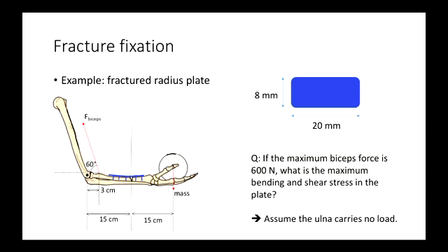So the way of thinking of it is, because you can calculate I in different directions, right? We're calculating for bending like this, so the cubed term is sort of weighting any dimension in that vertical direction. Because if that was taller, we'd have more bending resistance. Okay? So the cubed term is giving more bending resistance to any material in the vertical direction. So that's one way to do it.